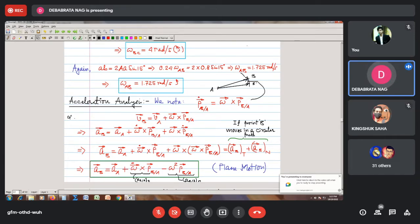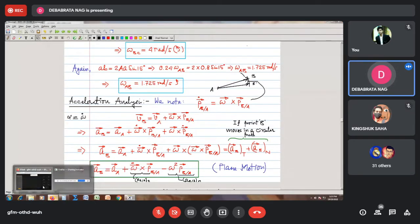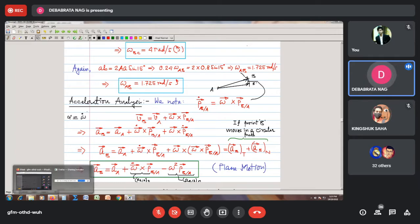So as a result, the scalar magnitude of angular acceleration is equal to the time derivative of the scalar magnitude of angular velocity. I told you the other day that when you study three-dimensional motion of rigid bodies in your next semester, you will find that the angular acceleration term is not so easy. It will also have a direction change component, because in three-dimensional motion the angular velocity continuously changes its direction. So you have other components in the angular acceleration expression.